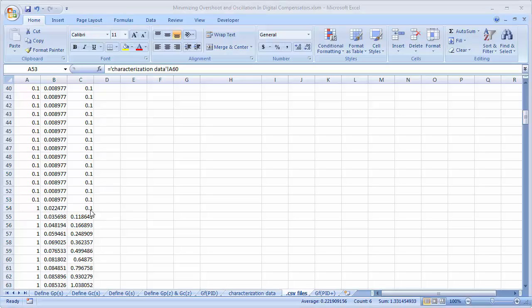In this example, the set point abruptly changes from 0.10 to 1.00. The plant had been in regulation at 0.10, so now the instantaneous error is 0.90. The compensator is computed, and the new plant command is issued. The plant response to the command issued in this time slot is measured after 1 unit of time, which is why the data appears to be skewed by 1 time slot. This is representative of how real data would be collected in a real system.